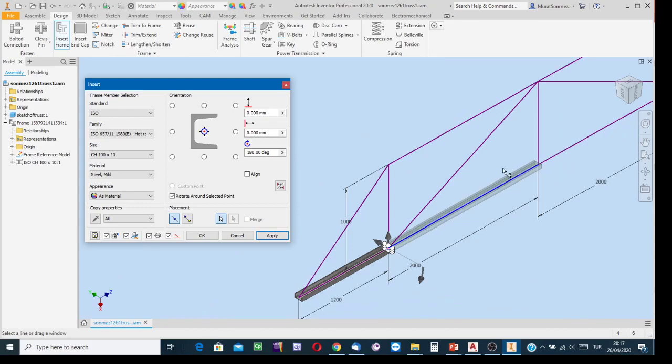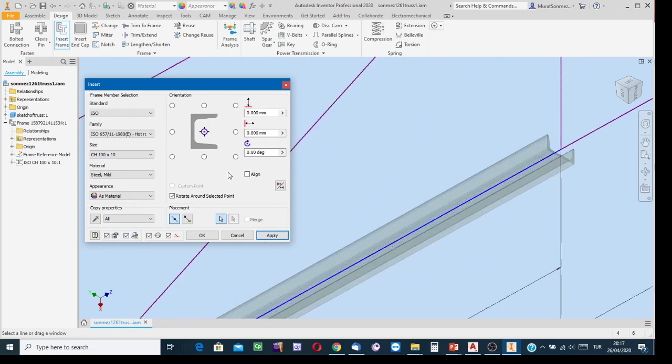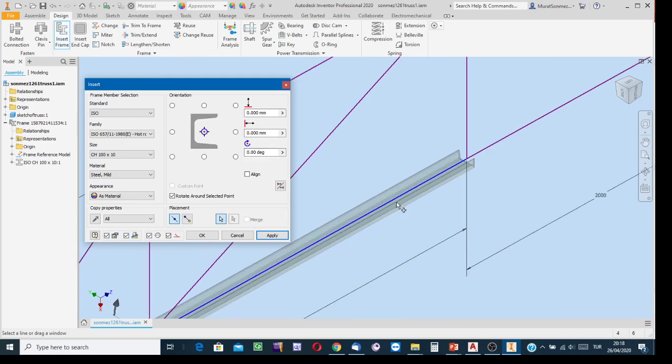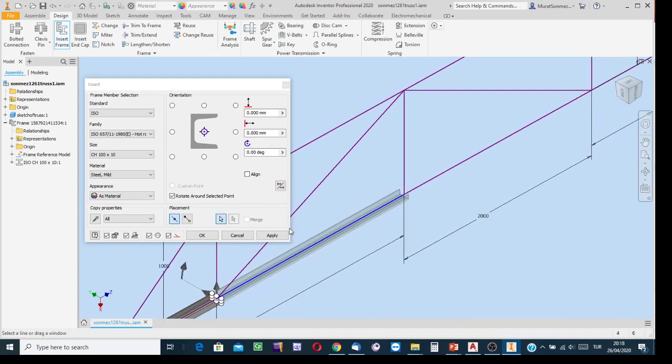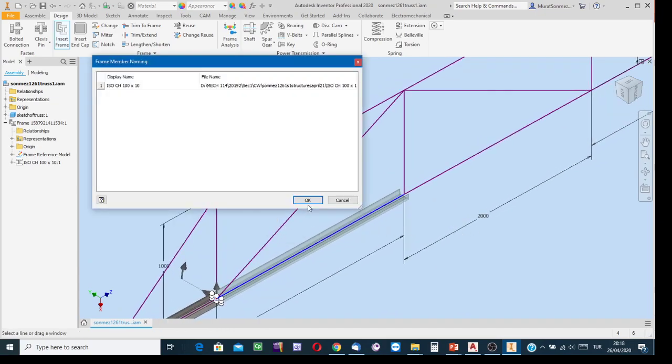Okay, 180 degrees rotated. But of course, it is the wrong positioning. I'm going to select 0 degrees. Yes, that is the function of this facility. Whenever the orientation of the member is wrong, see from the simulation whether it is to be rotated 180 degrees to orient it correctly, or 90 degrees, and then accordingly in which direction, clockwise or counterclockwise, select the angle options. And then, if you say that clicking the apply button for each and then the OK button